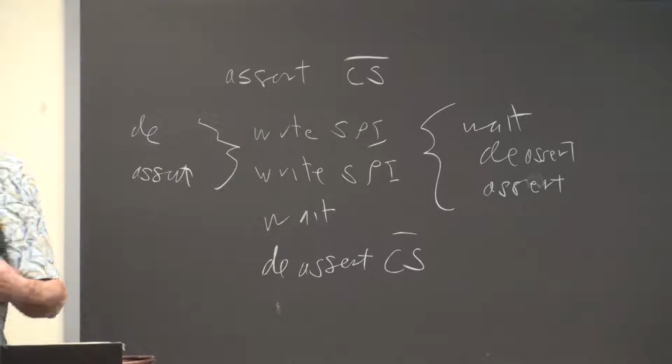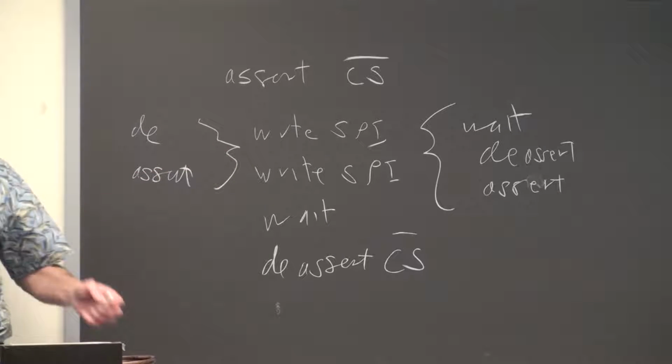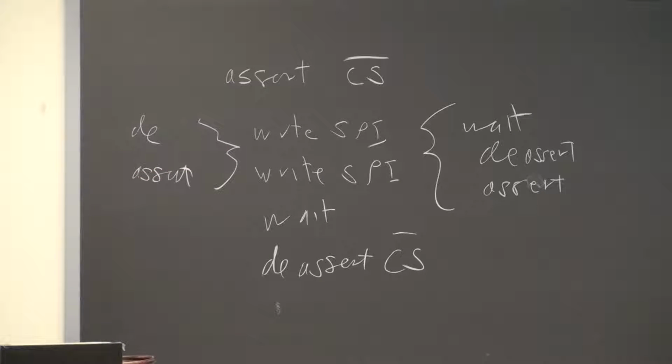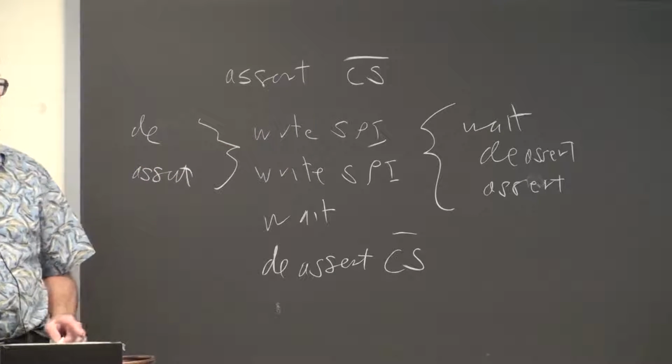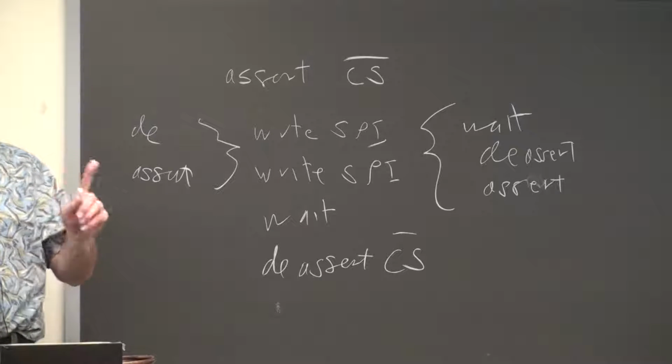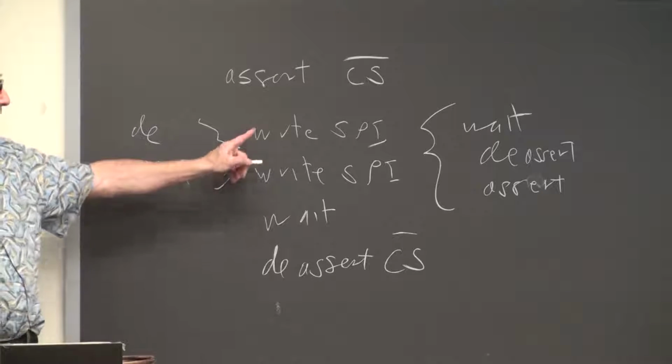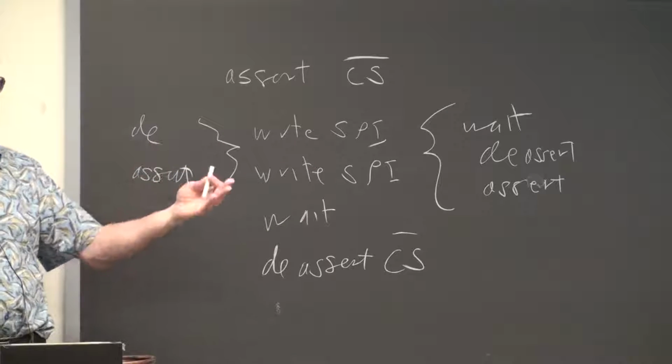The results you get by 2 fast writes in a row are really hard to understand. But what I think happens is that the buffer on the DAC is filled by the first write. It's a 16-bit write.